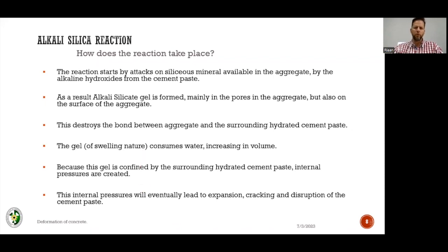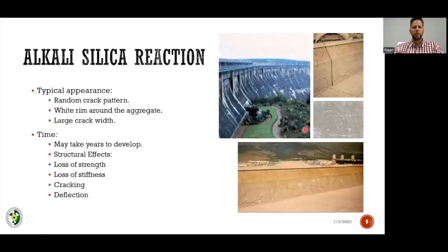That is absolutely horrible. And you will find some end products looking like this, a white substance leaching off the surface and cracking galore. It's cracking everywhere. This thing is cracking. These are not cracks that were put in the concrete when they mixed it. This is a crack that happens afterwards.